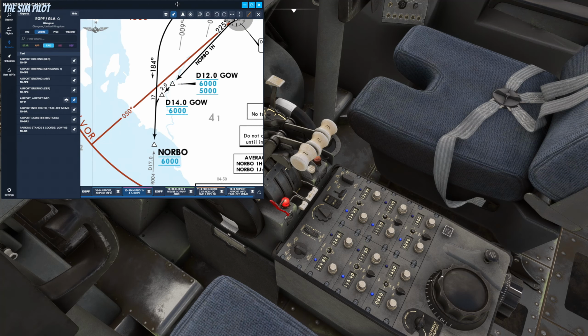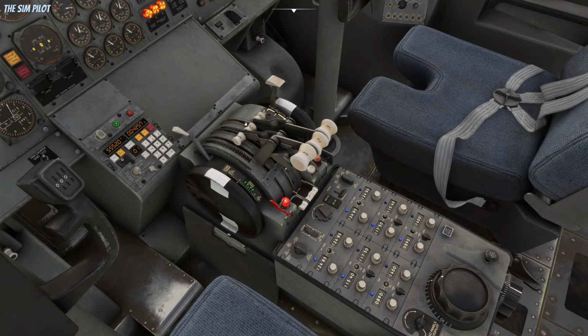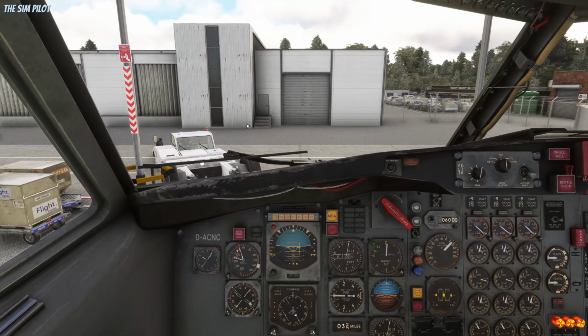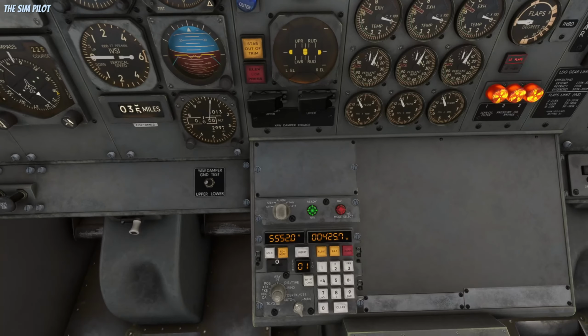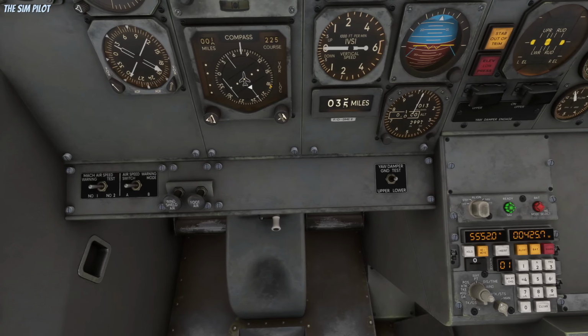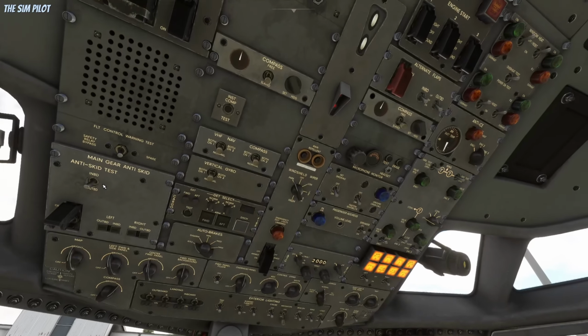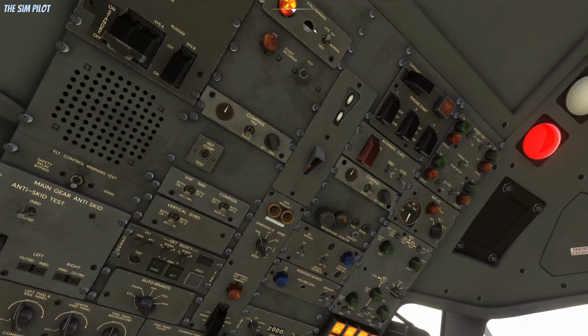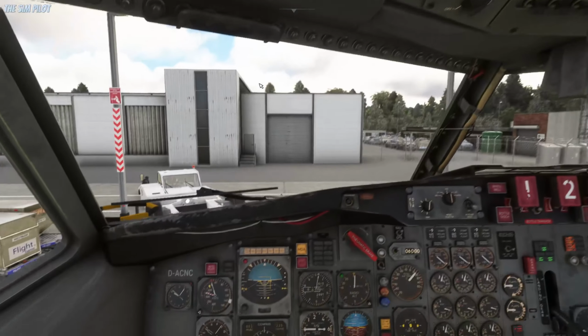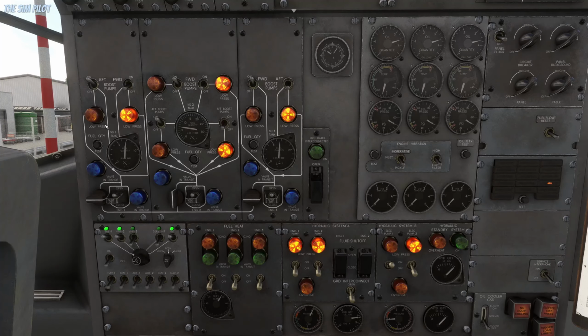And after that, we have completed the remaining of the tests. One thing left is, I can't remember if I did the max speed warning test. You can do this after start. And also the stall warning test, we haven't completed that just yet. Engineering station, we turned on one boost pump per tank, checked our fuel levels, and closed the crossfeed valves to wing tanks.